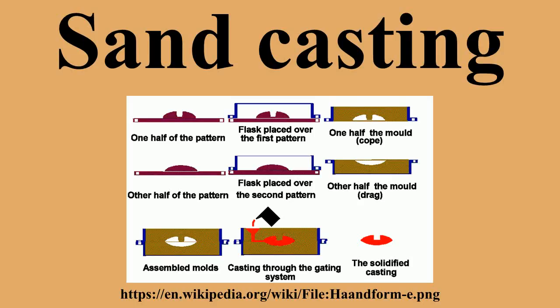In 1915, the first experiments started with bentonite clay instead of simple fire clay as the bonding additive to the molding sand. This increased tremendously the green and dry strength of the molds. In 1918, the first fully automated foundry for fabricating hand grenades for the U.S. Army went into production. In the 1930s, the first high-frequency coreless electric furnace was installed in the U.S. In 1943, ductile iron was invented by adding magnesium to the widely used gray iron.